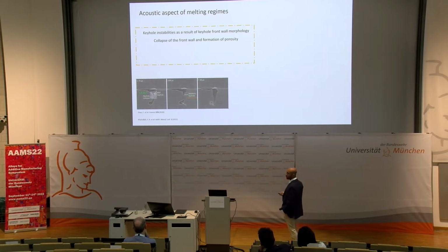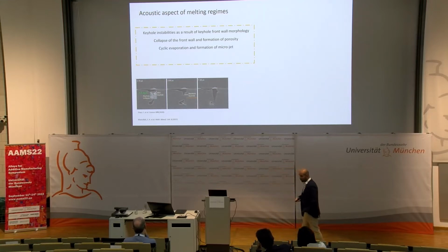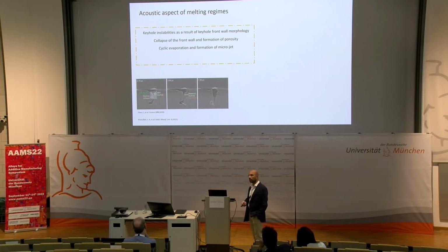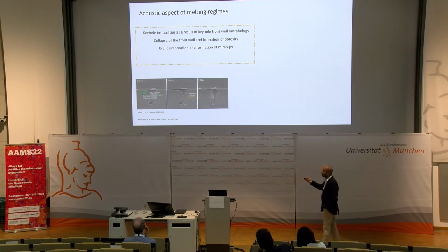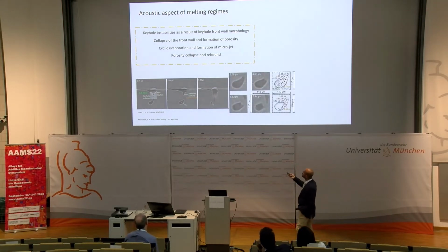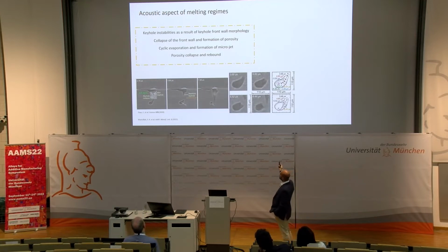Then you're going to have the concentration of energy in that newborn keyhole, which brings about cyclic evaporation and formation of microjets that can impinge into the liquid with speeds of 13 to 16 meters per second. Of course, they have their own acoustic waves. And if you're having a porosity, what follows is the porosity collapse and rebound due to this hammering pressure.